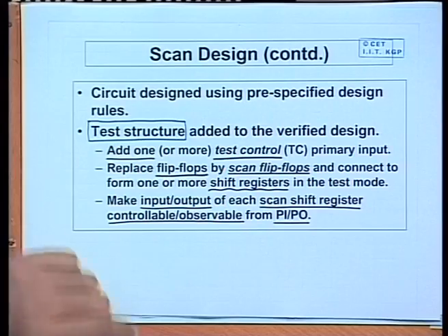So what we are doing here is that for all the flip flops in our circuit, we add some extra hardware so that if the test control is high in the test mode, they all become chained into a shift register. Now we have a long shift register; we can shift in any data pattern and load it with any known value.